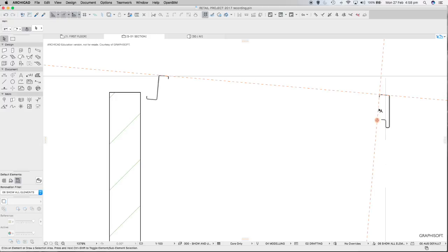So if you hover and wait for that guideline to come with its move circle, and if you come close to where we are at the moment, or even go a little bit further, you can see, I'm wondering if I go to 1400, that looks like it might be too much. So I think I'm going to come back to 1350. So if you offset that line there, 1350,